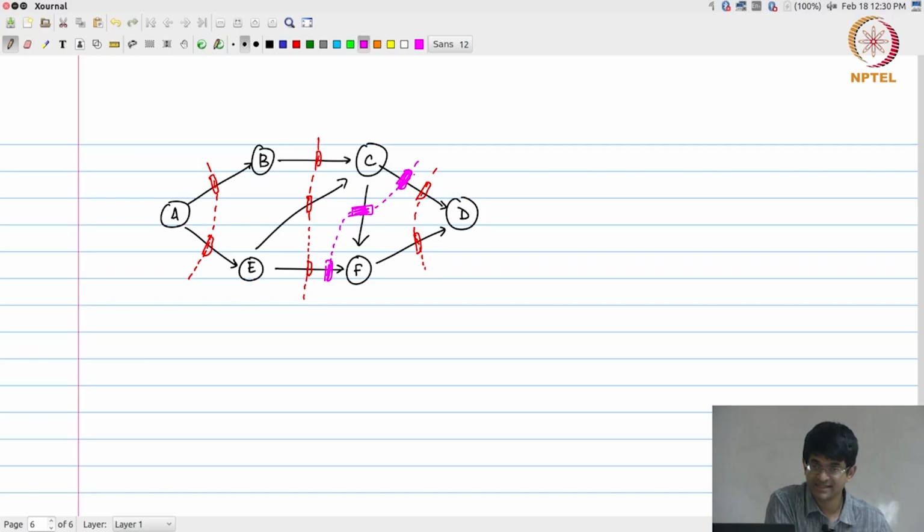The important thing is that it is at least one, because if I look at both of these, they both have two registers introduced on them, and that is important. Just the fact that I introduced a register over there for doing an earlier pipelining is not sufficient. If I also want to break the C to F edge, I need to look at the original graph, pick out a whole new set of edges and once again do the entire cut set part of it for them.